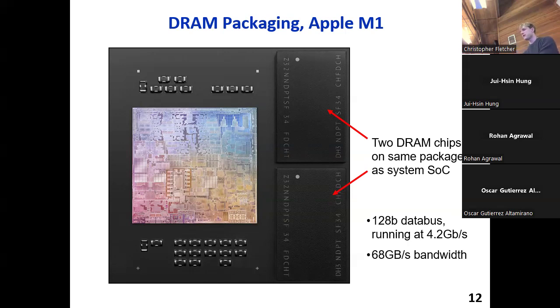The process of doing the access is driven by the DRAM controller, which is a custom circuit, usually these days at the edge of your processor die. But in the old days, it was off chip on a separate PCB called the Northbridge. That's what orchestrates accesses to the DRAM. Your CPU just knows about cache hits and misses, and it talks to the DRAM controller through that interface.